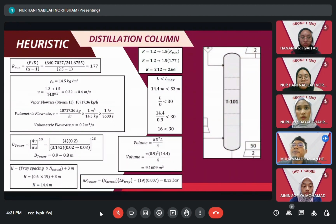Okay, from rule 1, table 11.13, the R minimum obtained is 1.77. From rule 5, table 11.13, the R optimum obtained is in the range between 2.12 to 2.66. From rule 2, table 11.14, we can obtain the volumetric flow rate. Then we can calculate the diameter of the tower, which is in the range 0.8 to 0.9 meter, and we have chosen 0.9 meter for the diameter of the tower.